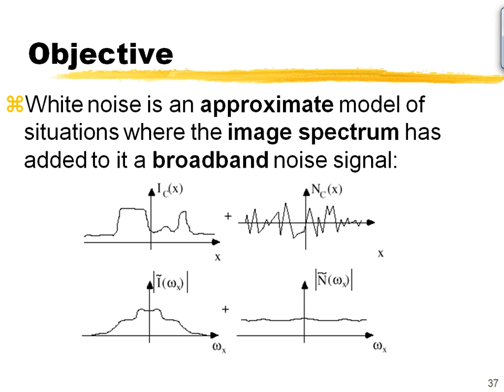So let's say we have our image. The image is going to have some signal, some distribution of frequencies. I have my noise, which is going to have a spectrum that looks like that, spread across all frequencies. If I look at their corresponding Fourier domains, an image is always band limited, we know that. But also, we know that it will always have larger energy in the low frequencies than in the high frequencies. So most images will have some Fourier distribution that looks like this. And the noise, we know it's going to be somewhat constant.